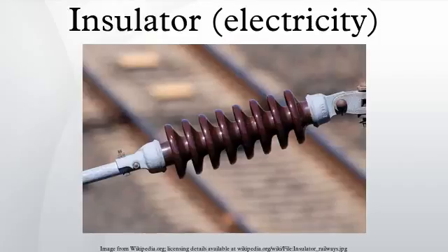Breakdown. When subjected to a high enough voltage, insulators suffer from the phenomenon of electrical breakdown. When the electric field applied across an insulating substance exceeds in any location the threshold breakdown field for that substance, the insulator suddenly becomes a conductor, causing a large increase in current, an electric arc through the substance.